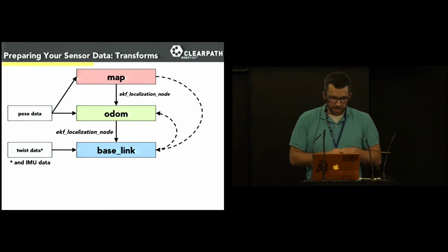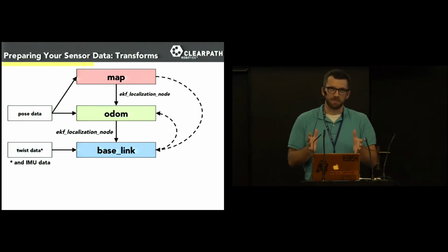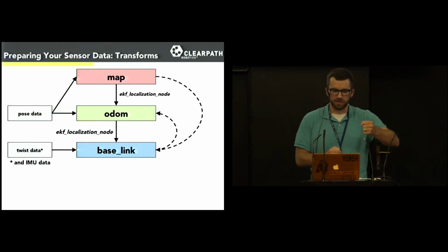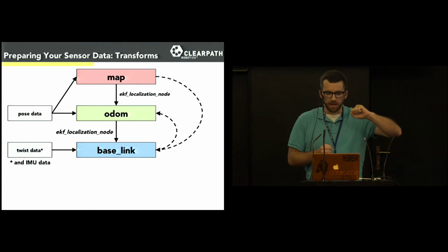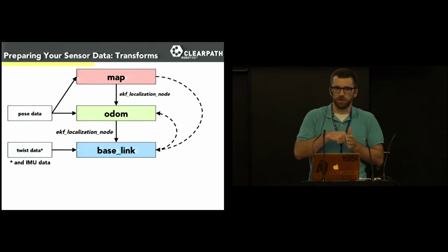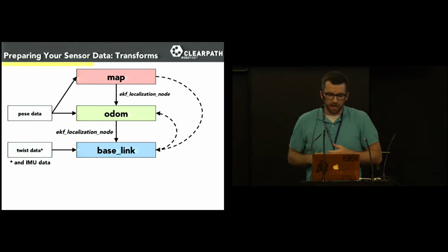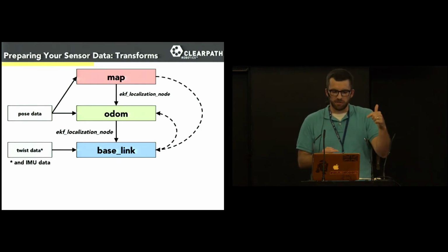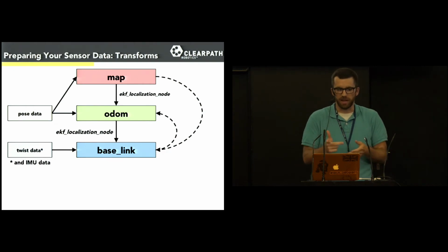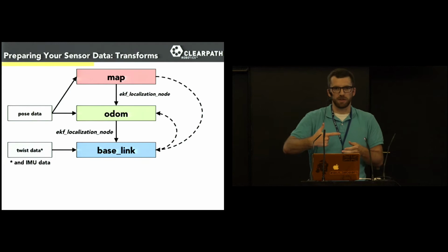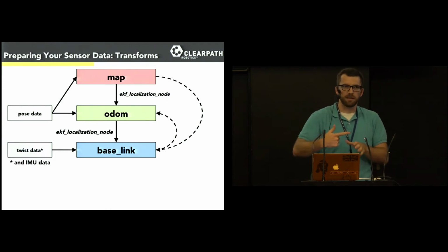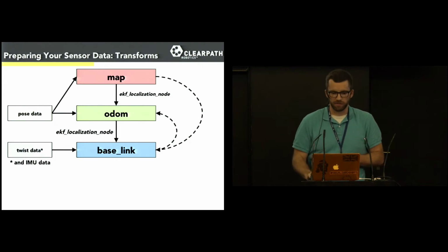The problem there is that IMUs are mounted with respect to some offset on your robot, right? And so that's the frame ID typically that people give. So they generate some static transform from base_link to the IMU frame. But then we need to use that information to correct the orientation in the IMU. So if you imagine an IMU that's facing left, for example, then in the IMU frame, if you go like this, it's obviously pitching, but yet the robot itself is rolling, so we need to correct for that.